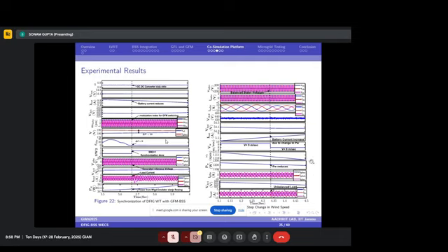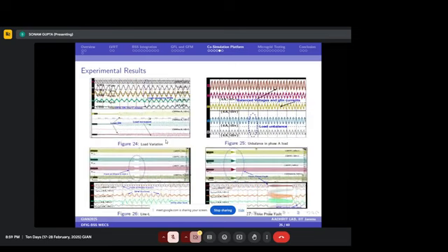Second, we have checked for the step change in the wind speed, and the other transient cases also, to ensure whether this co-simulation platform is validated for only one condition, or only steady state condition, or also for the transient condition as well. So we have checked it for the line to line fault and the three phase fault conditions, and we have seen that with the change in the load, or at the time of the fault, due to the presence of this grid forming control and its capability of providing grid stability, the wind turbine will